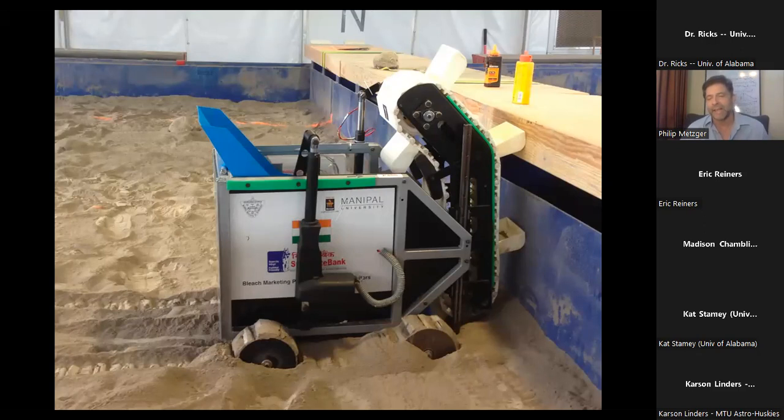And then to get out of that hole, that robot has to drive uphill. So it's got to lift its own weight up several centimeters while trying to shear the soil on the uphill. And it just can't do it. The shear strength of the soil is not enough.